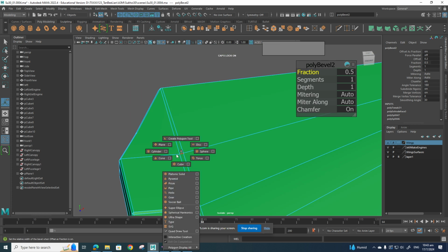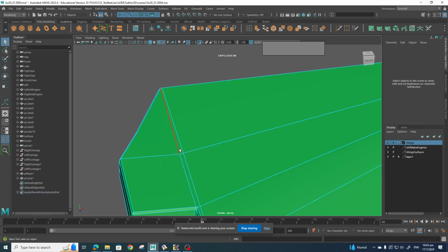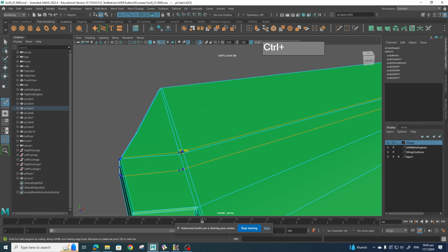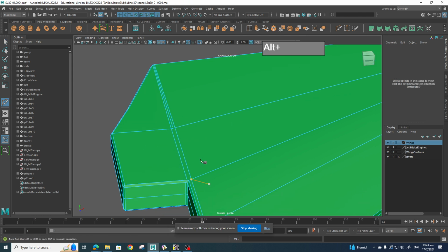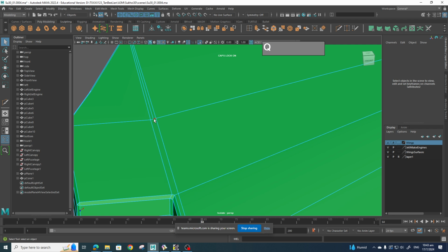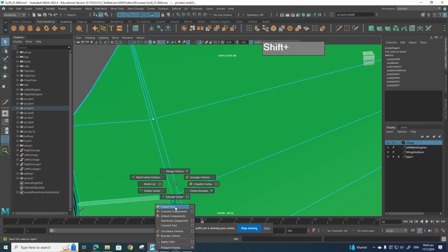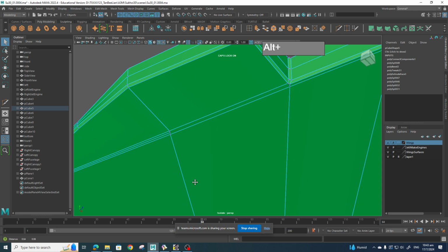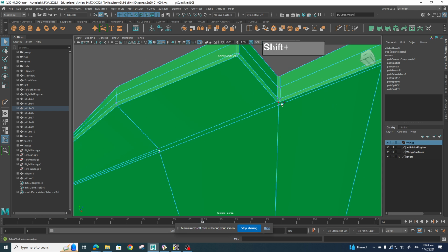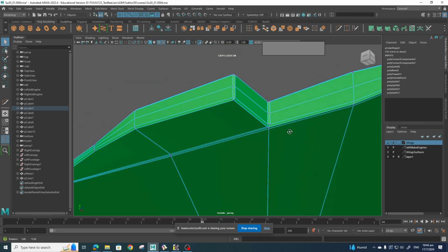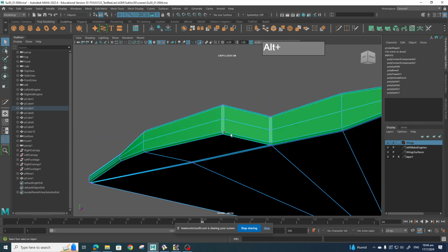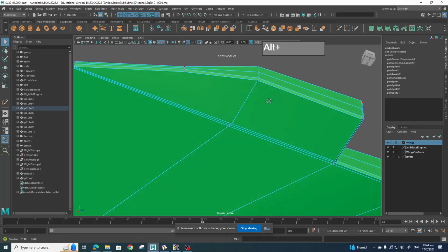We got a multi-sided face over here, so we can fix that by doing an edge loop. So I'm going to insert one edge loop over here. Shift right mouse click and then middle mouse click here, and then we will select these 2 vertices and connect them. Connect components, go to the other side, select these 2, press G, repeat last command, and we should get rid of that. I got a couple of triangular faces here, but I think we can leave those alone.